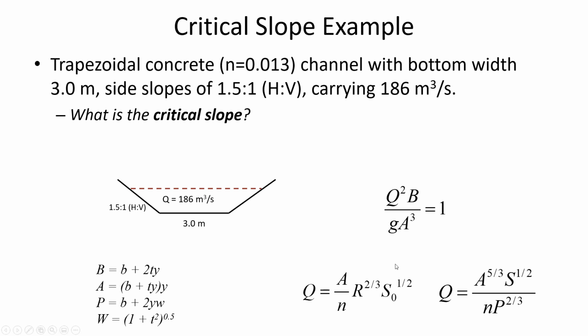And we want to know what slope will cause the critical depth. So here, this equation we can use to find the depth, the critical depth, and then once you have the critical depth, you can put it into Manning's equation and solve for S. So it's a two-step process. Step 1, find YC, the critical depth, using this equation of Q squared divided by G is equal to AC cubed divided by TC. Well, top. I think that's B. The top width when conditions are critical. Okay, so find the depth with that.